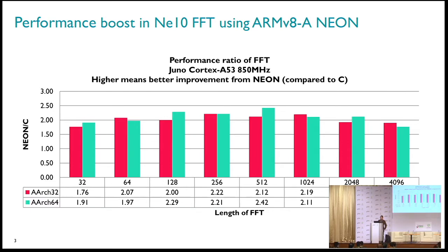When you do an FFT, it's not one single function call, it's actually two function calls, where you first pre-allocate the twiddles, and then you do the FFT, right? Only the FFT routine is measured. The alloc and free are not included, because we always alloc once, and we can perform the FFT many times.